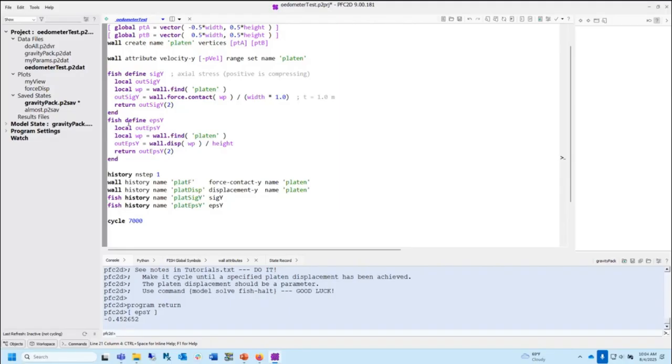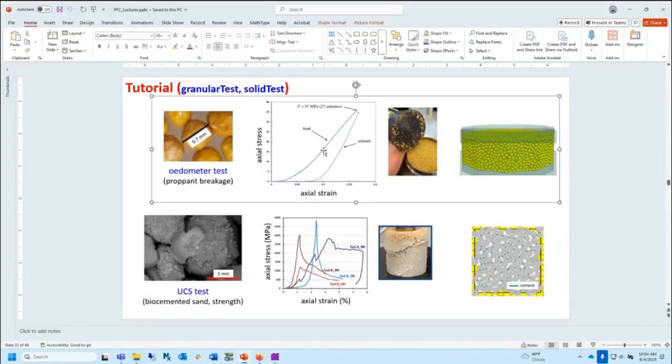It's just a clay porosity mass, and you want to plot that versus time. Here you go. You use the history mechanism. You make a FISH function, use the history mechanism, right? So this is the basic thing, and now we're going to continue on with this, and it's going to be your challenge to figure out, let's see if we can now choose properties so that we can get this curve.